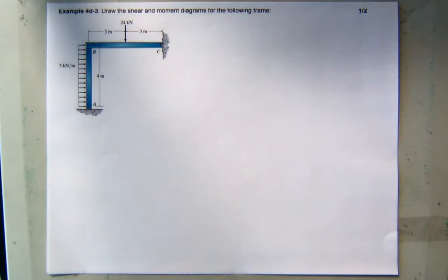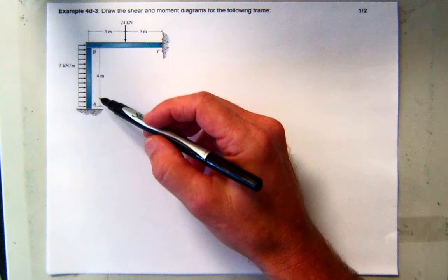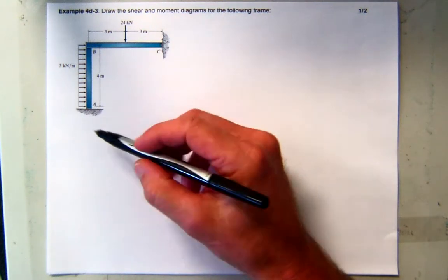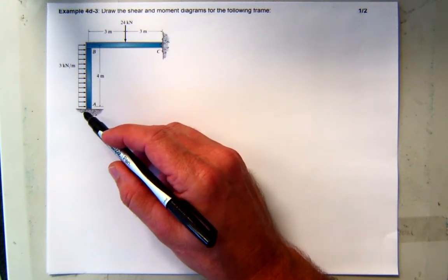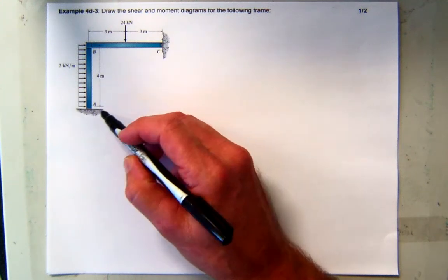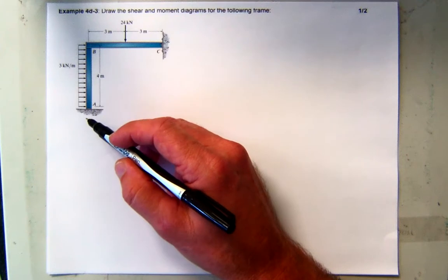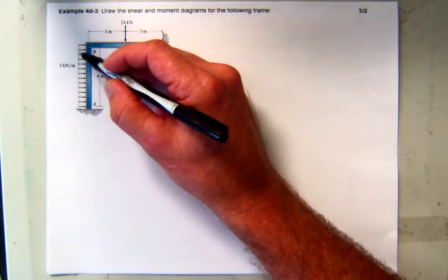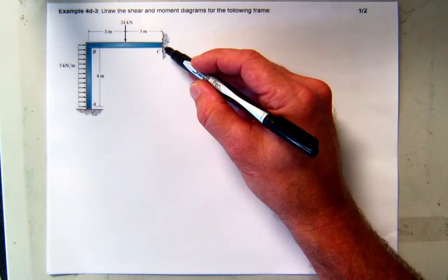All right, so let's work on this one. Now, this is another pretty simple frame that has two components. This is a little tricky. It's hard to see here, but this is just like a roller support. It looks like the frame is allowed to slide in the X direction, but not in the vertical direction. It's fixed at B, and then over here at C is a pin.